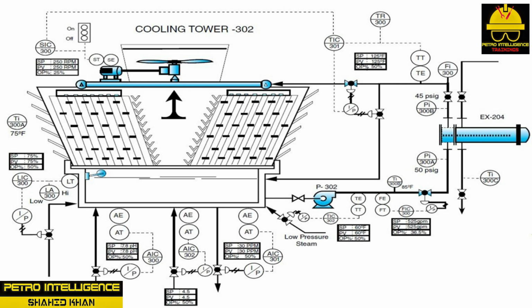This type of heat transfer relies on the principle of evaporation. When this process occurs, heat from the water is absorbed by the airstream that raises the relative humidity to near 100%. These heated currents are quickly dissipated by the wind. Cooling tower 302 is an evaporative heat rejection device that can significantly reduce water temperatures.